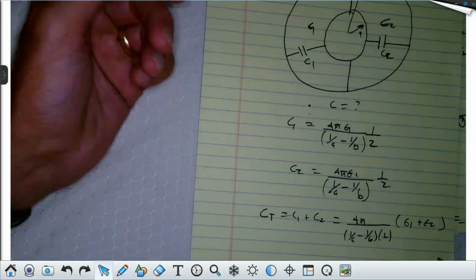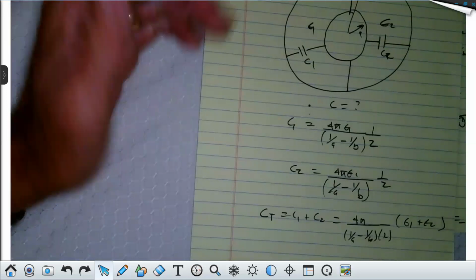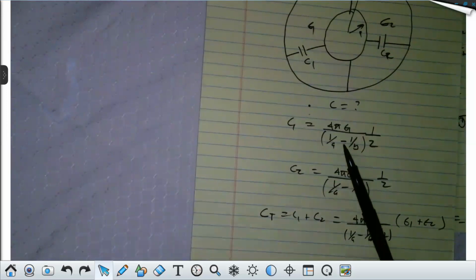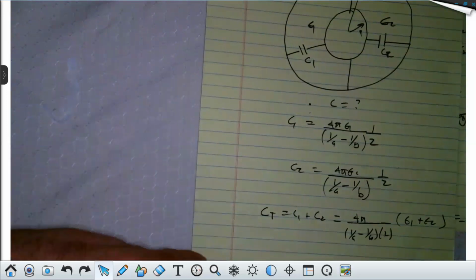And so it could be parallel or series. Just remember what I'm showing you. If you can see how you can partition into either a parallel or a series region and calculate just that capacitance, then you can add them accordingly. If they're in series, it's 1 over C1 plus 1 over C2. If they're in parallel, it's just C1 plus C2. Follow me? How many understand that principle, class? Just make sure I understand that you do. Got it? All right.